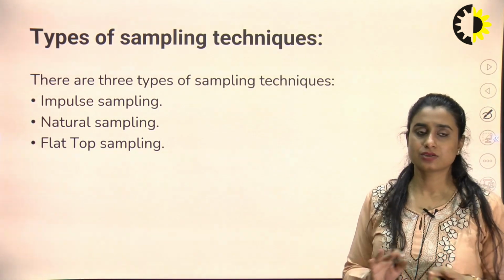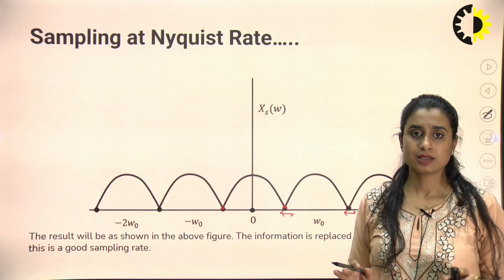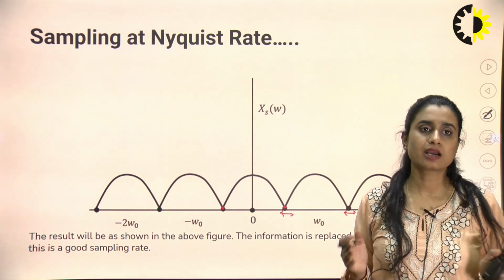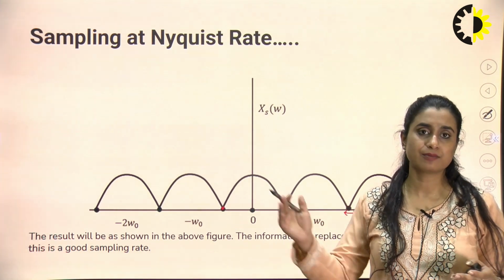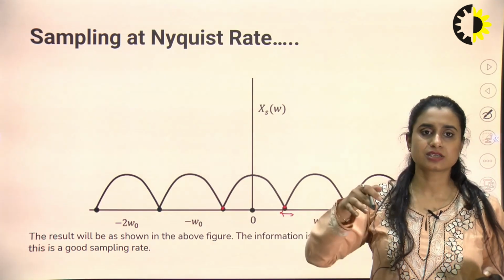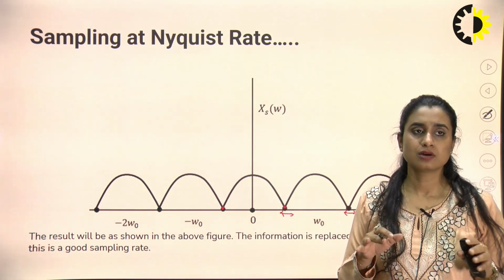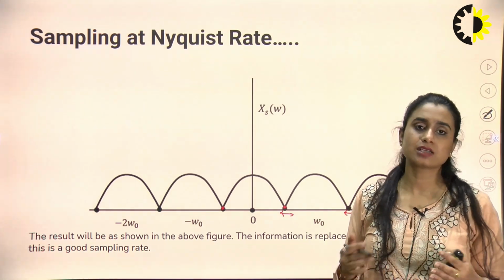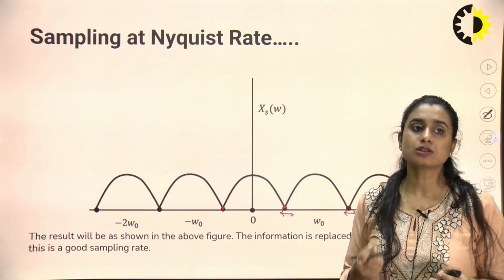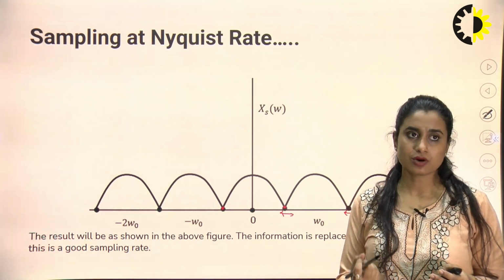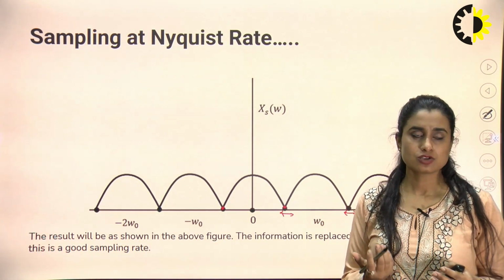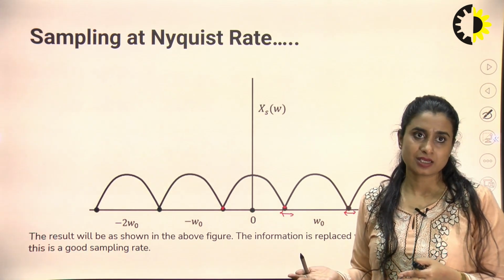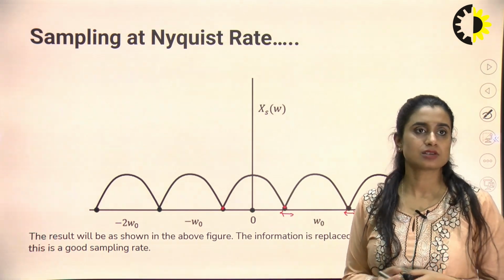Now, after this, it is clear that we have to strictly follow the sampling theorem in order to make our communication successful, so that when we retrieve our signal at the receiver and reconstruct it, we are able to retrieve it most appropriately. And what are the ways to prevent aliasing? We may use low pass filters, also called anti-aliasing filters, before sampling. Those low pass filters will help me prevent the aliasing effect, right? So to prevent aliasing, we may use low pass filters.